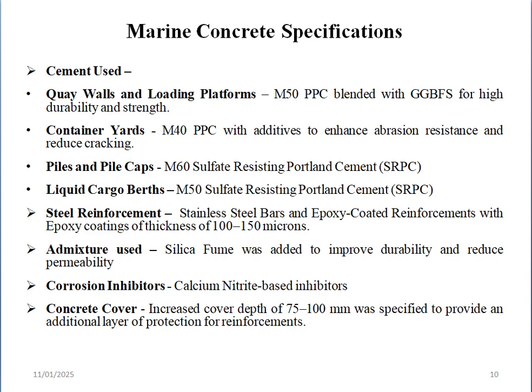Piles and pile caps: M60 sulfate resisting Portland cement. For liquid cargo berths, M50 sulfate resisting Portland cement was used. Steel reinforcements: stainless steel bars and epoxy coated reinforcements with epoxy coating of thickness of 100 to 150 microns.